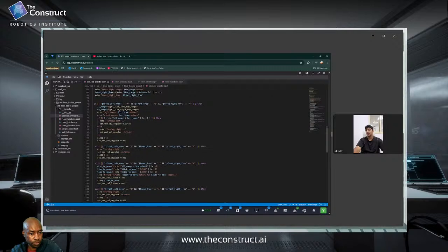The way it works is you have an if condition. It checks all the different parameters, and in this case it's using three simultaneous checks: the front left, front, and the front right. If they're all 0, then it checks again, and it reports so and so meters for the left, so and so meters for the right.